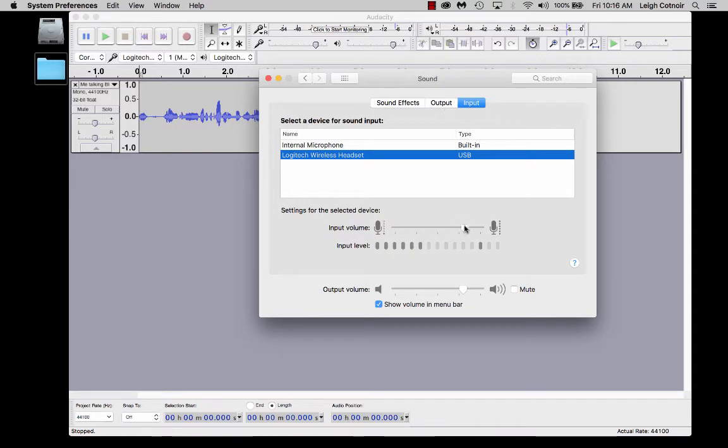The other thing is that you can change your input volume here. If you turn it all the way up, then what's bound to happen at some point if you talk very loudly into the speaker is that you might get clipping up here. Once the bars start coming up really high in this area where I'm moving my mouse, the amplitude can be so great that it's beyond the ability of that particular microphone device to actually capture it, so it'll clip it like it's giving it a haircut. And that's how you create distortion, and it sounds not good.